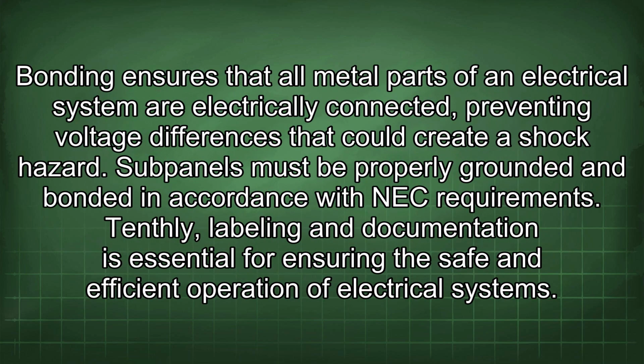Bonding ensures that all metal parts of an electrical system are electrically connected, preventing voltage differences that could create a shock hazard. Subpanels must be properly grounded and bonded in accordance with NEC requirements.